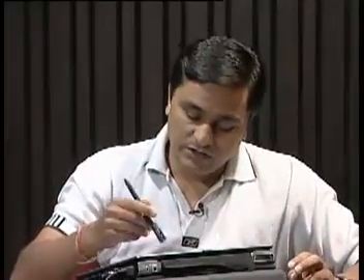So, now the receiver can determine the difference between its own counting, which is 4, and the counting which is received here, which is 1. By finding this difference, which is 3, so 3 could be 3 seconds or whatever, it is able to determine how long it took for this 1, which was started by the satellite, to finally reach the receiver. So, this is how basically the time is measured.